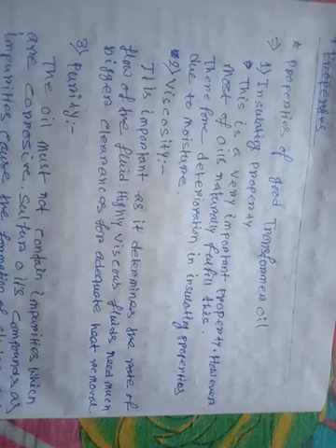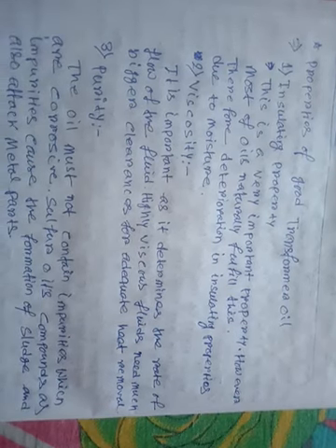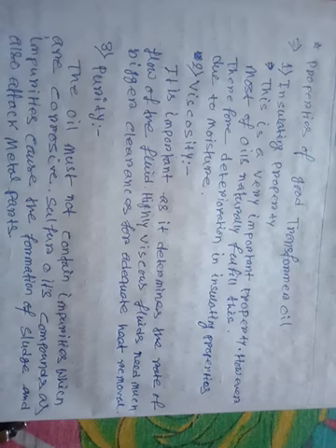Third point is purity. The oil must not contain impurities which are corrosive. The oil must be moisture free. There is no mixture with the oil. The transformer oil is totally free from moisture, water and different types of liquid material.